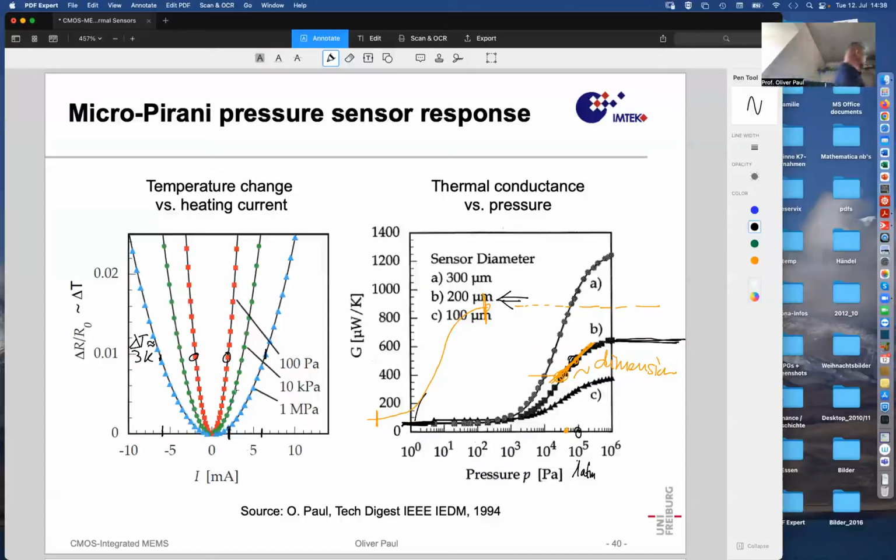And so there is a way to translate pressure into a current information, because if I have a system that maintains the temperature of the membrane constant, independent of pressure, so it adjusts by putting more or less current so that the temperature is constant, that current varies with pressure. And the current is then the measure of the pressure. The current says how much the pressure will be. I have to calibrate that, of course, but it will be the information carrying the information about the pressure.